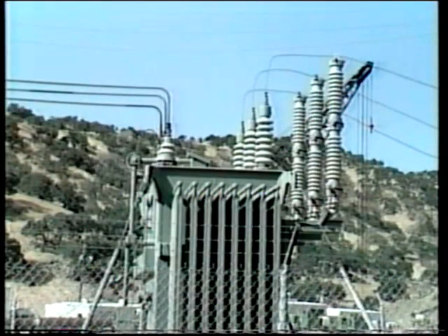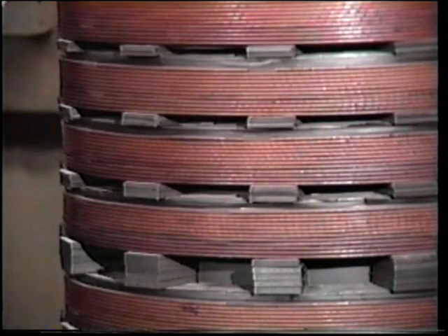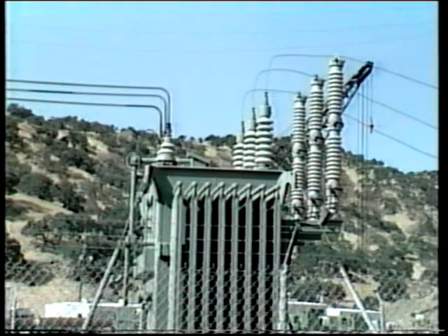Generally, power transformers are three-phase. That is, the primary and secondary windings of each phase are wound on three legs of a common iron core, all immersed in the same tank of insulating oil. Single-phase transformers are also used, connected to form a three-phase bank. Any combination of Y or delta connections can be made to give the desired voltage levels and phase relationships.